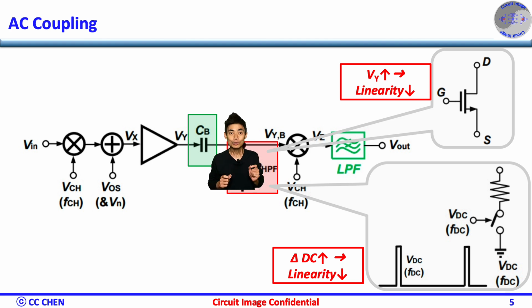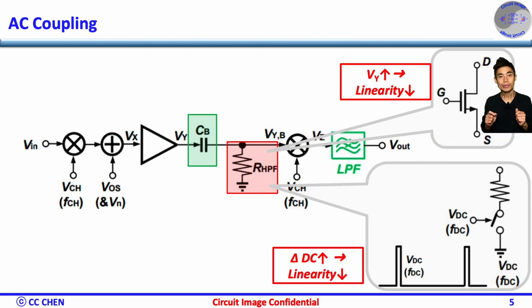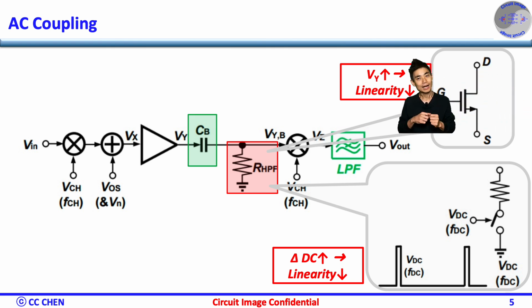Unfortunately, we need to keep the signal content such that the high pass cutoff frequency must be very low. Therefore, to fit a reasonable area on a chip, we could apply a few picofarad capacitance with the MOSFET transistor in the off region as a voltage controlled resistor. Is this good? Probably not.